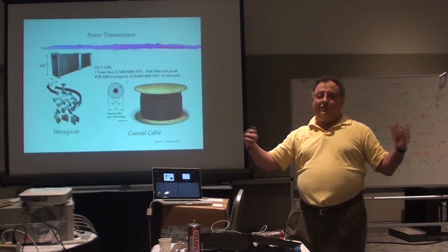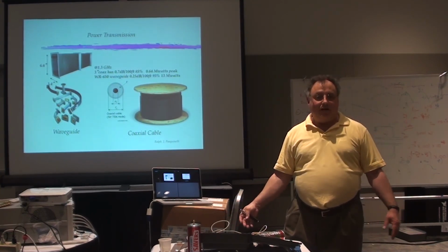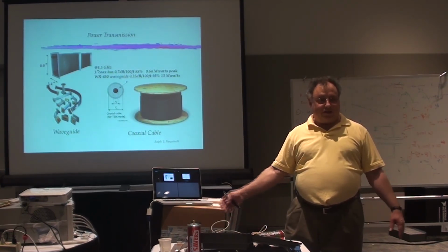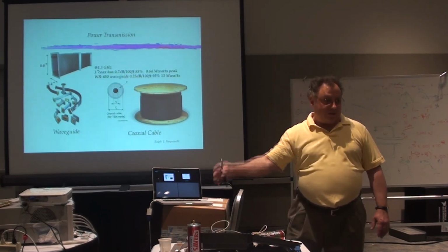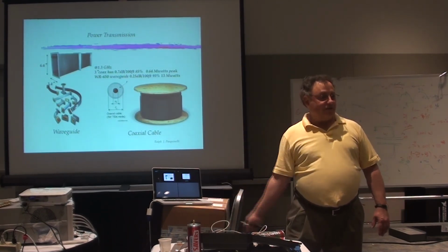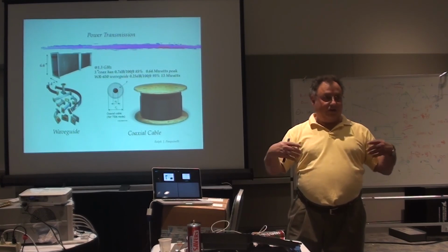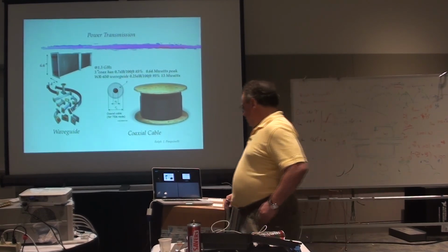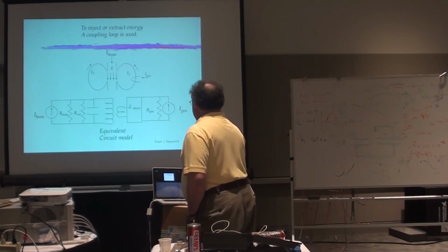Waveguide wasn't an option because when you take a look at the characteristics of the waveguide, it's very dispersive. Again, not all frequencies travel at the same velocity, so I don't have a linear transfer function with them. Okay, so now we're starting to put the whole thing together.